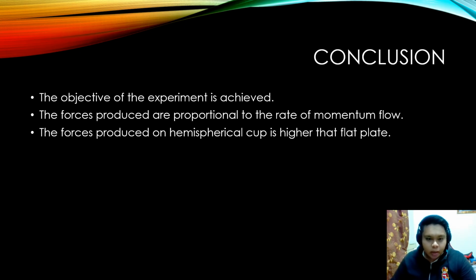So in conclusion, the objective of the experiment is achieved. The forces produced are proportional to the rate of momentum flow, and the force produced on the hemispherical cup is higher than on the flat plate.